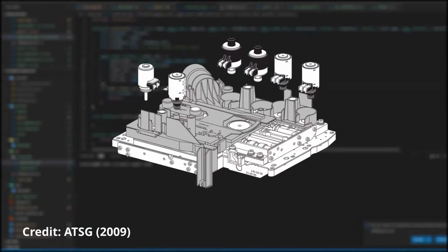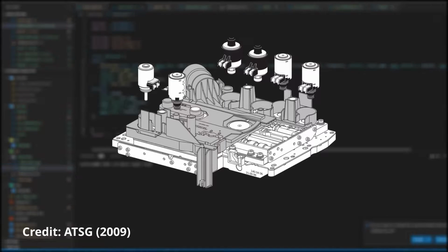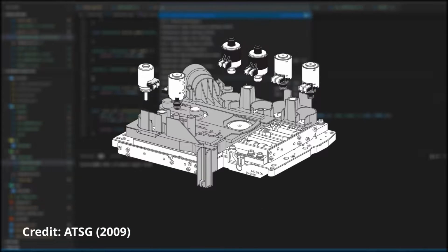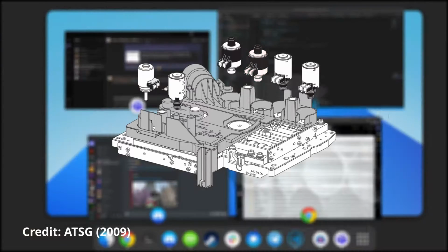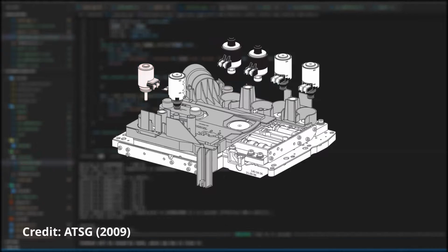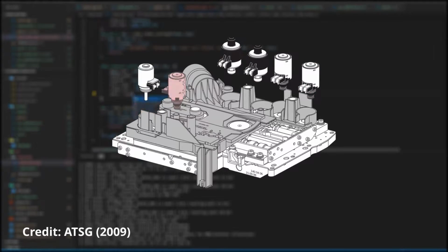4, 5 and 6, these are called shift solenoids. These solenoids are only activated during shifting and allow the pressure to flow from the shift pressure solenoid through the valve body of the gearbox in order to apply the correct clutch or brake for the target gear of the gearbox. For simplification going forward, I will be referring to the solenoids by the technical names Mercedes gave them: SPC, shift pressure solenoid; MPC, modulating pressure solenoid; TCC, torque converter solenoid; Y3, 1 to 2 and 4 to 5 shift solenoid; Y4, 3 to 4 shift solenoid; and Y5, 2 to 3 shift solenoid.